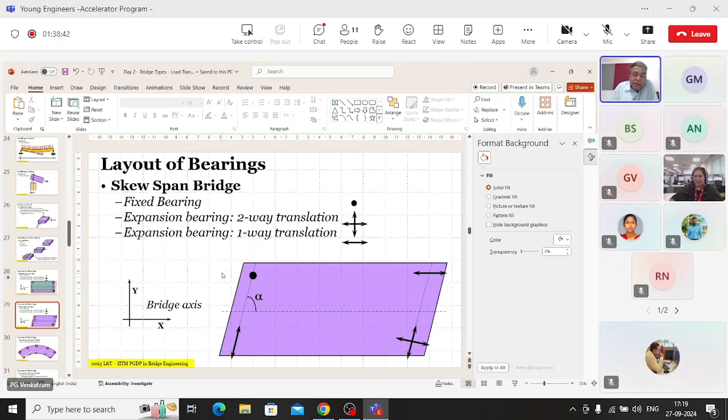Why will it not? See, the idea behind expansion and contraction is this length will reduce, this width will reduce. And if it reduces in that direction, you will always have this permitting movement and that permitting movement. And this anyway permits movement in all directions. So that means when there's a reduction, the reduced cross section will be like that. When it is expanded, the expanded cross section will be like that. So will there be any stresses in this arrangement?